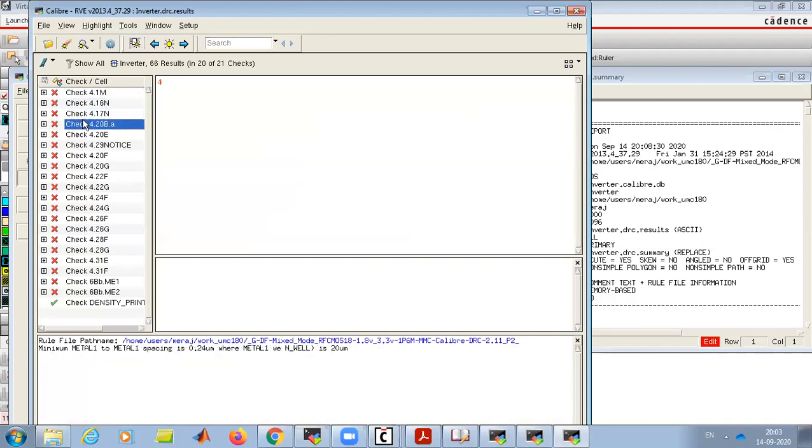Okay, so you mean the channel length that we are going to use in the transistors is going to be the minimum distance between any such metal plate or any such object? Yes. These are the rules. You can see that for metal 1 to metal 1, the spacing should be at least 0.24, that is, micrometer you should have a distance, if the width of your line is less than 10 micrometers. So these are the standard rules which have come from the foundry.